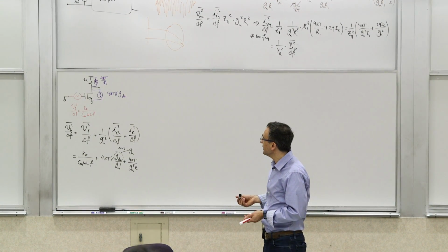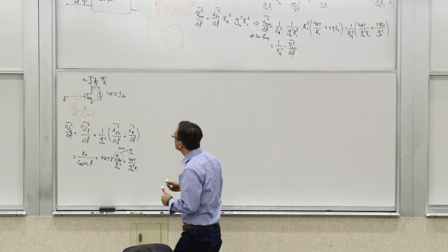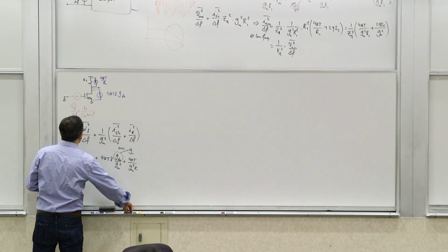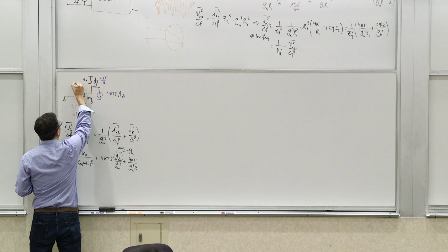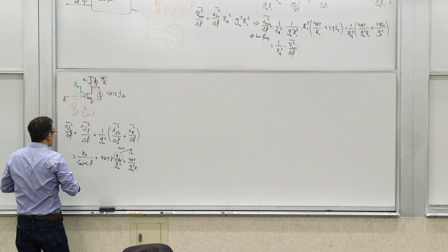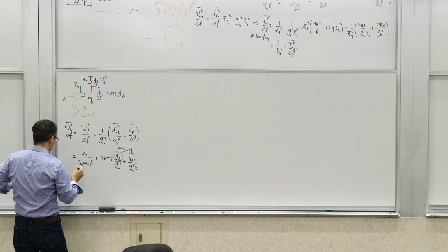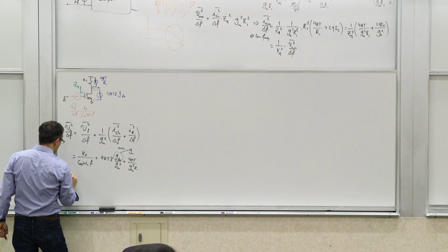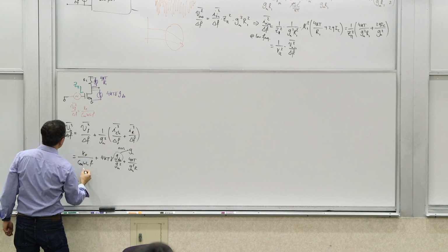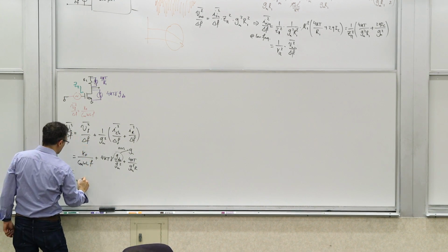And if you do a current source, then it's related essentially through the impedance that you see here. So if you look at this impedance looking into here and call it Z pi, and you want to look at the equivalent input current source in general, it would be basically the same thing as the voltage except for the Z pi.